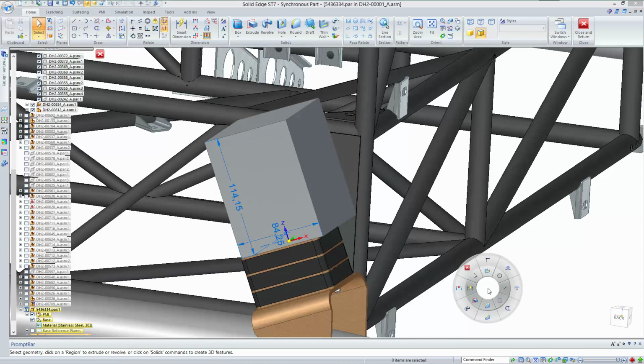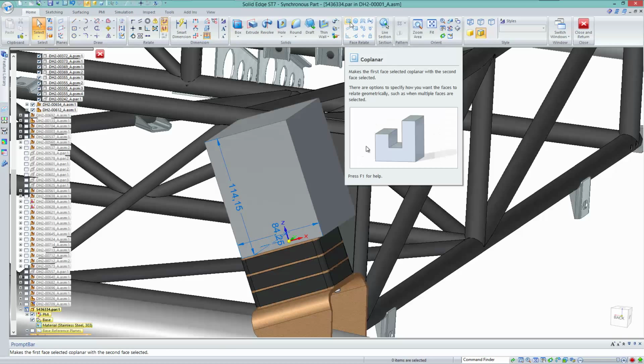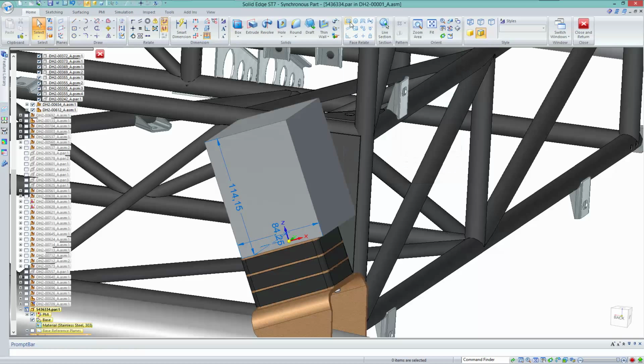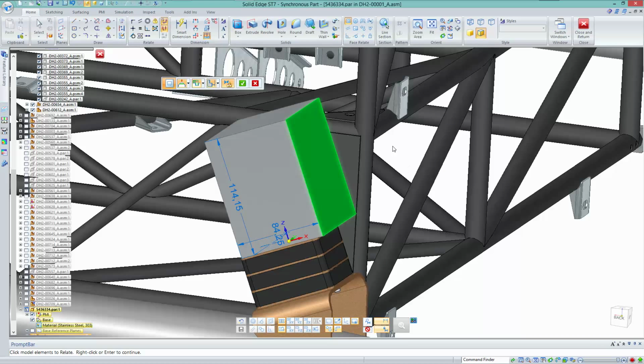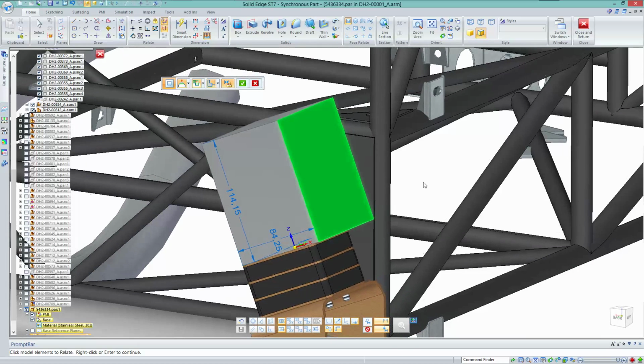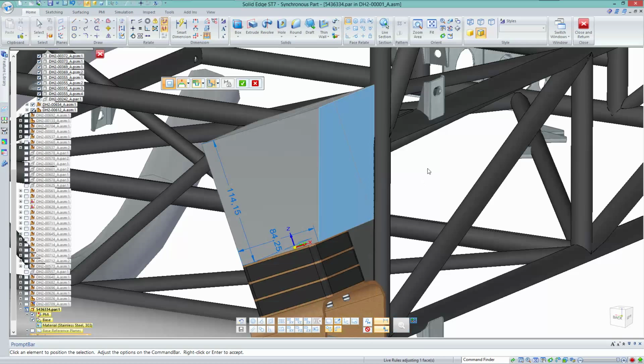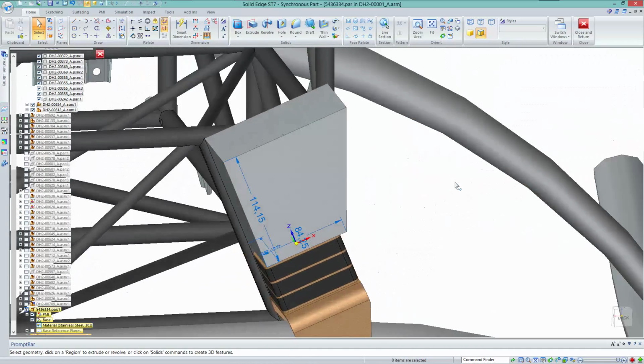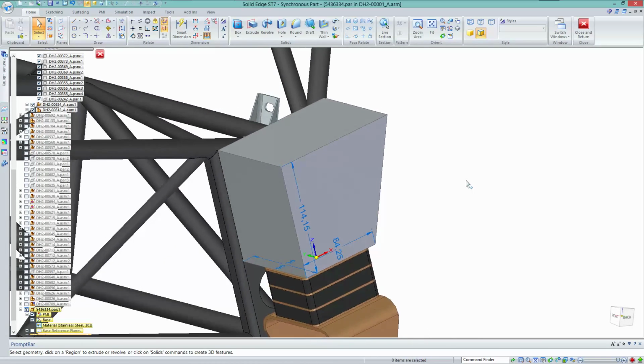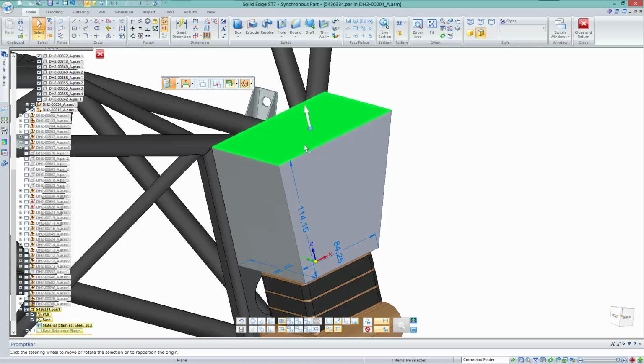Something else that we can then do is, again, using some of these face relationships. I had a quick look at the radial menu, but the face relate I was looking for wasn't in there, so we can just run it from the command ribbon at the top. A couple of clicks and we can get that face located, and that's not too bad. We're getting there already, actually. Something else I'd like to do is, rather than just selecting a face, have a quick look at this steering wheel in a little bit more detail.